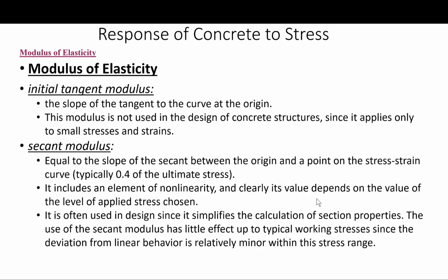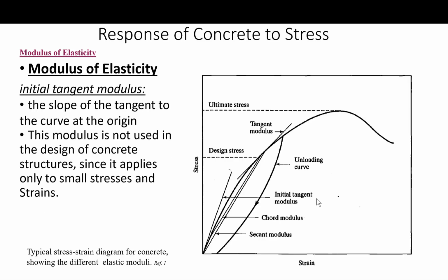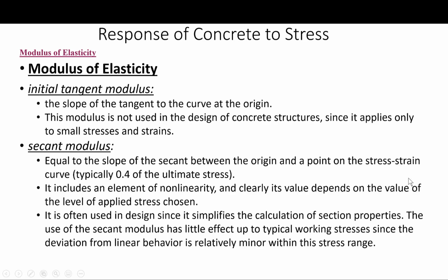A more practical measure of the modulus of elasticity is the secant modulus. Let's go back. Okay, this is the secant modulus. This is equal to the slope of the secant between the origin and a point on the stress-strain curve.